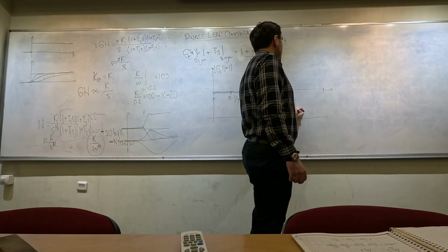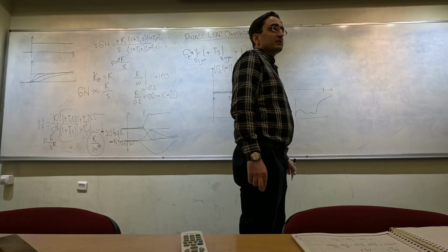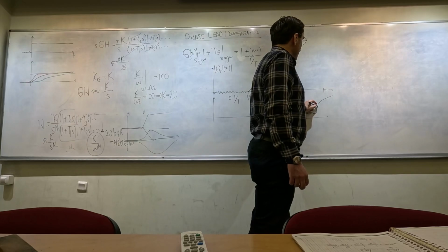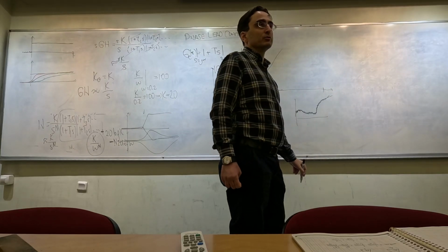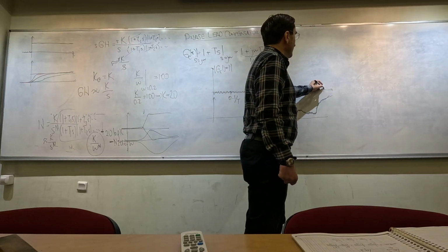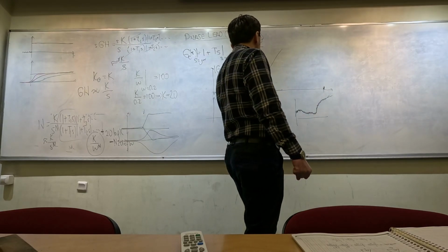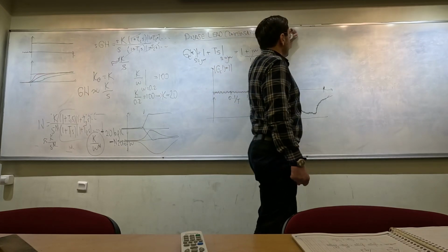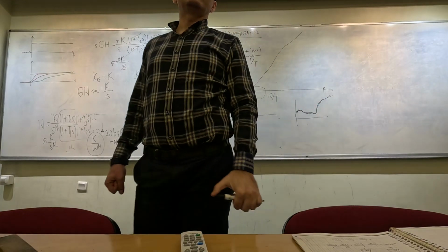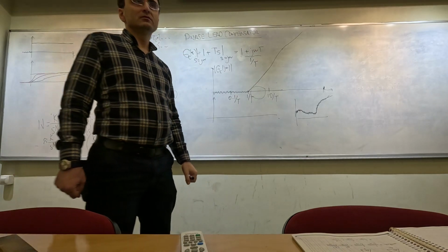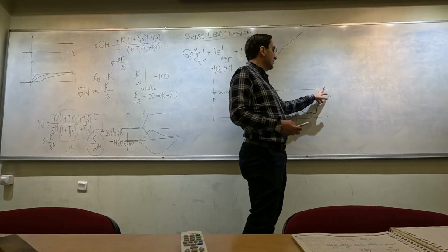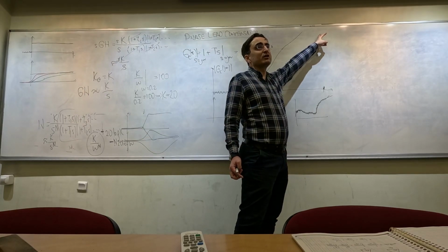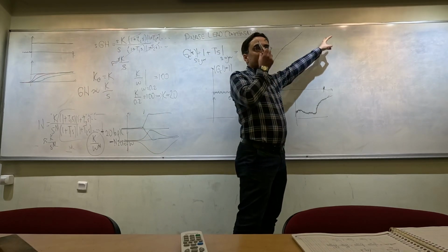So if this is the input that I am going to give to the system, usually there is this type of noise which is going to come on top of that input. So noise is somewhere here in frequency, and the signals of interest are somewhere here. Do you think this type of transfer function for a controller is fine for us then? It is not fine. Why is that? Because the noise here is going to be amplified with a very, very large gain. I won't like this.